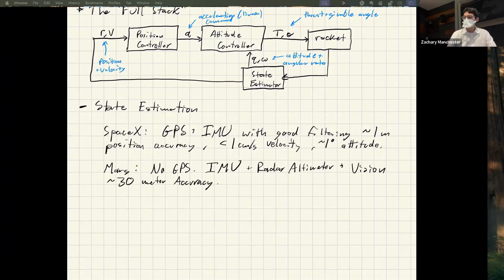But again, you're not really trying to fly to a pinpoint landing because you're like 10 kilometers off by the time you pop the parachute, because of the initial uncertainty being about a kilometer when you hit the atmosphere and then dead reckoning through the atmosphere with your IMU. By the time the parachute pops, you're kilometers off. The powered descent phase doesn't happen until you're pretty low and you don't have enough fuel to do a 5-kilometer traverse with that thing. So you're really at this stage just looking to avoid boulders and find a good flat landing spot.